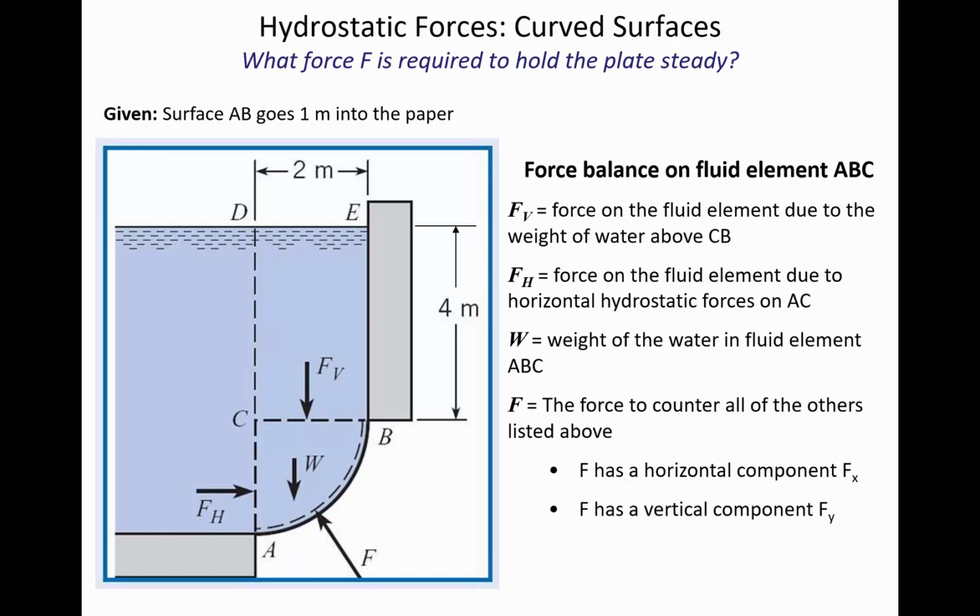So remember earlier I held a piece of paper up and I said the gate is like if you take a flat piece of paper representing a metal plate and then you bend that and now it's a quarter circle. So you're looking at in the webcam there a quarter circle. And so the vertical projection says, what does that look like from the front? So it's a curve from the side, but from the front it just looks like a rectangle.